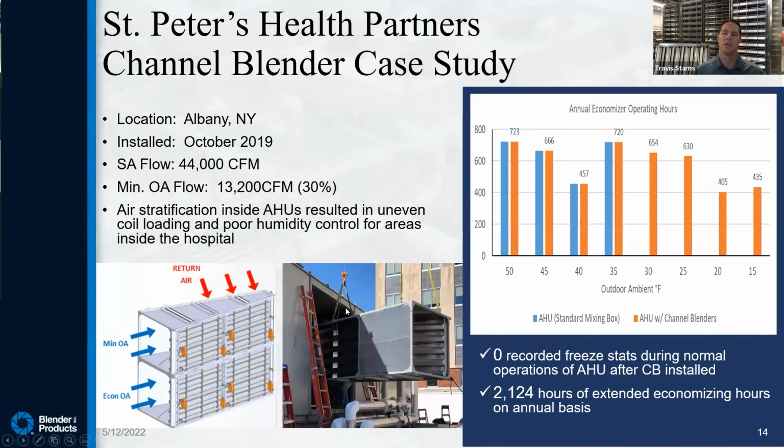If you can imagine, there were 4 large industrial fans mounted on that steel beam. The idea was, can we take the outdoor air that enters from the side and blow it across the plenum so it can effectively mix with the return air coming from the back wall? At the end of the day, none of those field retrofits were the optimal solution for them, and they continued to have operational issues. So they retrofitted this with channel blender technology.